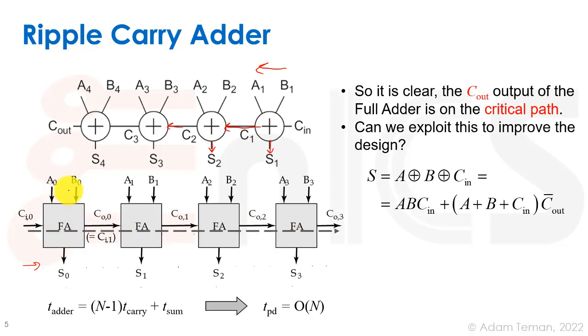So that's a ripple carry adder, or looking at it with a better view using full adders: using A0 and B0, and the Cin 0 is going to be 0, we take out the sum of that and the carry of that, bring in the carry with A1 and B1, and get the sum of that and the carry, and we keep on rippling until we get to the final sum and the final carry.